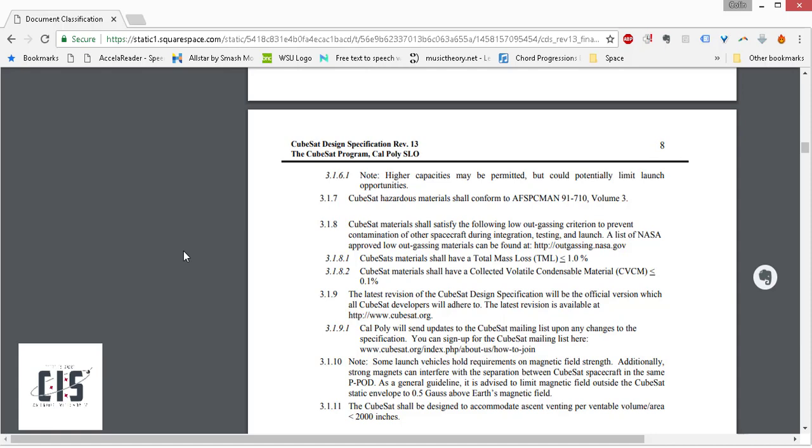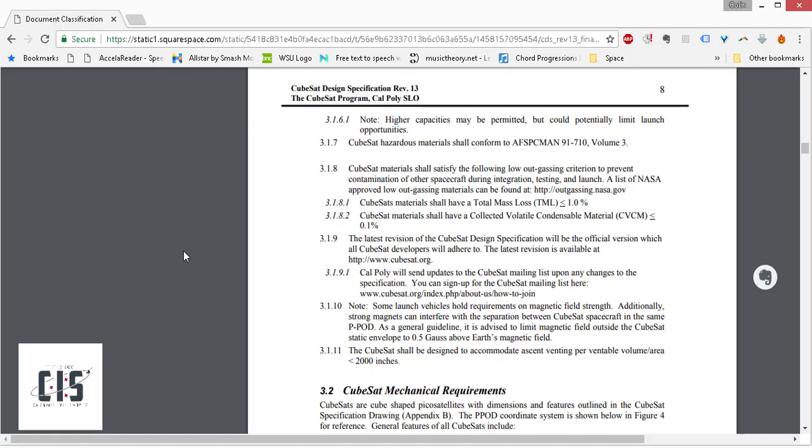Oh, okay. So materials for use in... Oh, that's good. So for people who want to Google general materials to not use in a vacuum, which is space, mind-blowing, search on Wikipedia "materials for use in vacuum," and they have a nice list of materials to avoid, which include everything from what he stated to PVC and different types of plastics. There's a ton of stuff here. So knock yourself out. I was not even aware of that, but that's definitely a good source to have. You do need to go back and check whether the total mass loss is less than the limit. But that's a good place to start, and then you can verify that. Cool. I did not even know that.